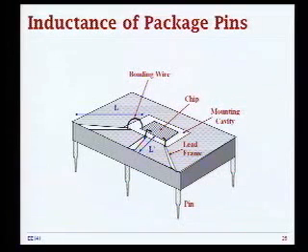And this is really when you need to consider these transmission line effects, because in the PCB you have printed circuit boards of a size of maybe 30 centimeters, and you know already that the speed of your signals is really fast on the chip, so you would like to propagate those signals onto the PCB so you can test your chip. And basically this analysis that we are going to go through is really applicable for the PCBs, because you know that wave propagation speed is about 30 centimeters per nanosecond, and that's about the numbers that you're talking about in the PCB design.